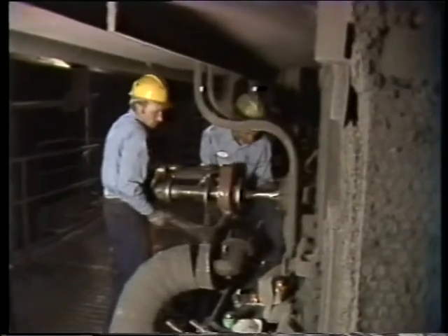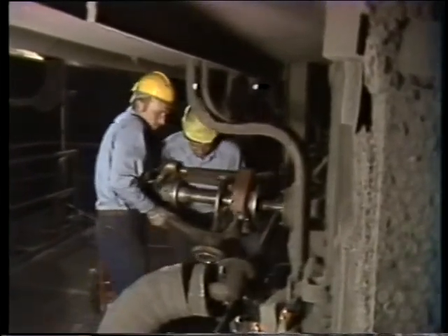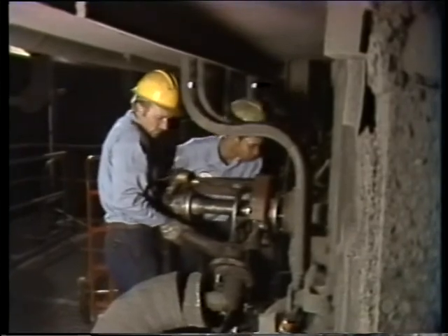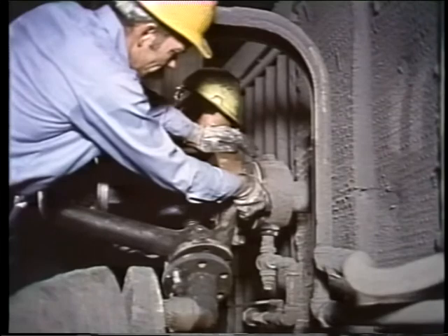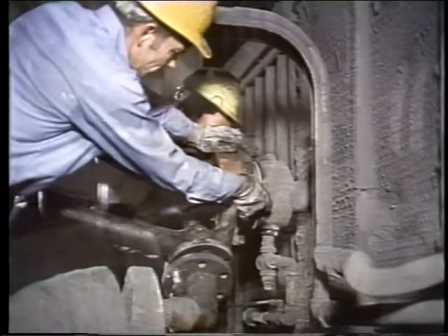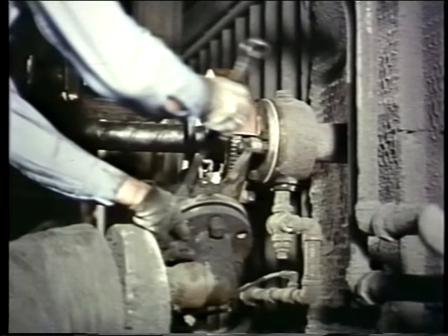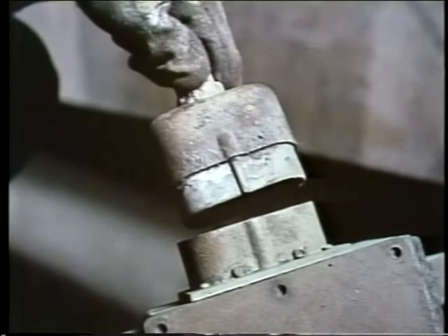When gasket surfaces are clean and new gaskets fitted, the soot blower is maneuvered into place and bolted up. The mounting on the boiler wall is snugged up first to hold the soot blower firmly in the proper position. Then the flanged connection is tightened to the piping for the blowing medium. After the soot blower is mounted firmly, it is reconnected to its source of power.